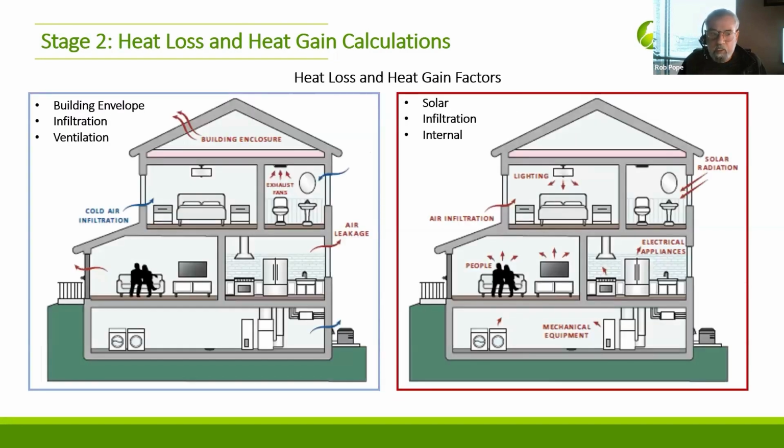avoiding load calculations. And load calculations are pretty straightforward. What we want to know is how much heat is lost in the winter, for example, and how much is gained. One is the heat gain, one is the heat loss. And it's impacted by things like the insulation, window U values, solar heat gain coefficient, how leaky the house is, infiltration, internal loads. All these things are taken into consideration.